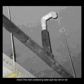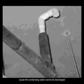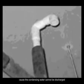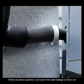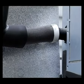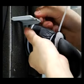Check if the main condensing water pipe has a vent or not. If the main discharged water pipe is jammed, the condensing water cannot be discharged. If there are the above problems, they can lead to water leakage of the indoor unit. Please modify it according to the requirements of the technical manual.